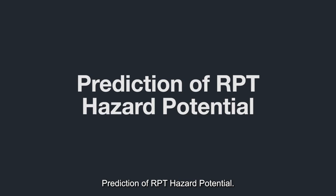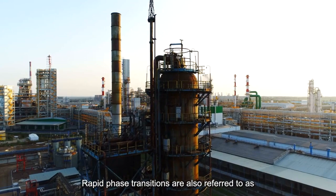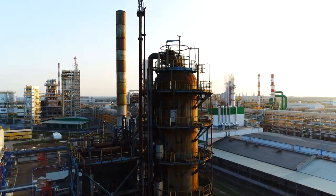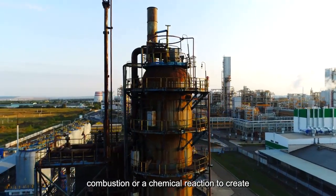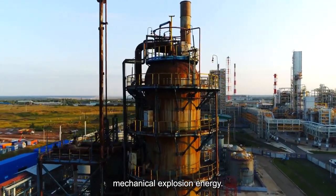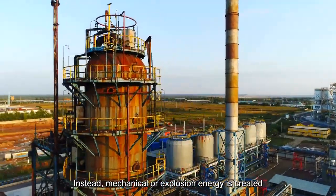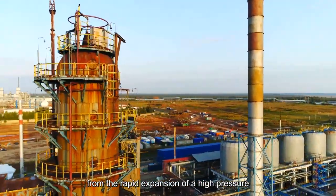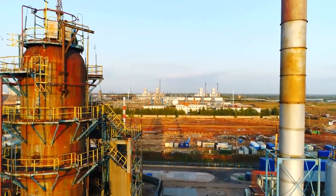Prediction of RPT hazard potential. Rapid phase transitions are also referred to as physical explosions. This type of explosion does not involve combustion or a chemical reaction to create mechanical explosion energy. Instead, mechanical or explosion energy is created from the rapid expansion of a high-pressure metastable fluid to ambient pressure.